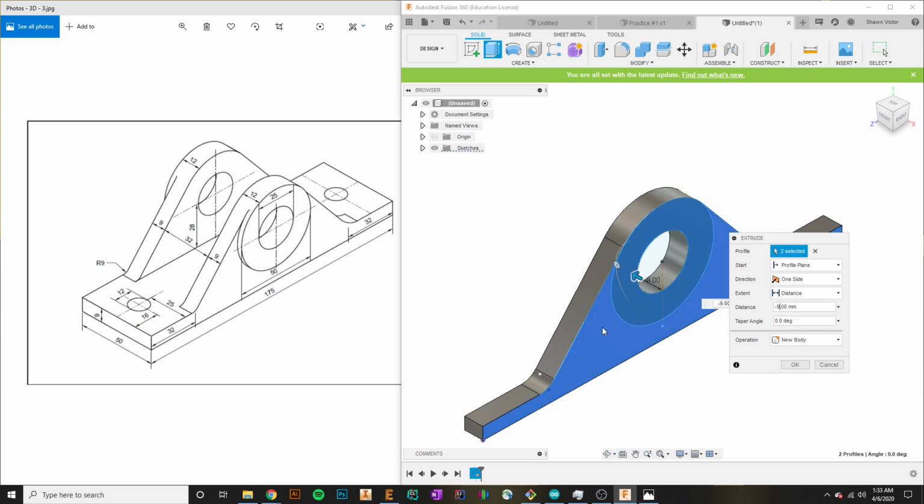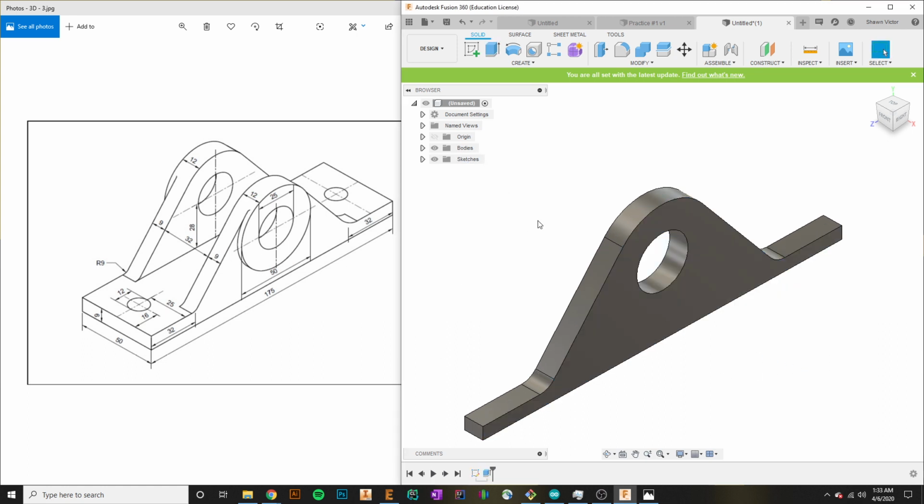Okay, that gets us this portion. You hit OK. Now, one thing that this feature has is this part of the circle is also extruded outwards. In our case, they extruded out by 12 minus 9, so by 3 millimeters. So you can see that that sketch disappeared whenever we actually did the extrude.